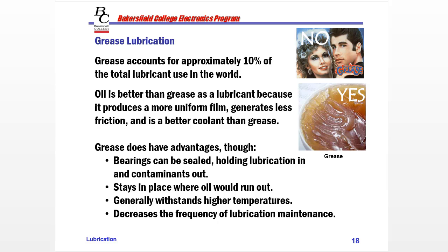Now, oil is better than grease because it can produce a very uniform film across and coating all of the metal surfaces. It is thinner, so it generates less friction. And it's also a better coolant than grease. But grease does have advantages.